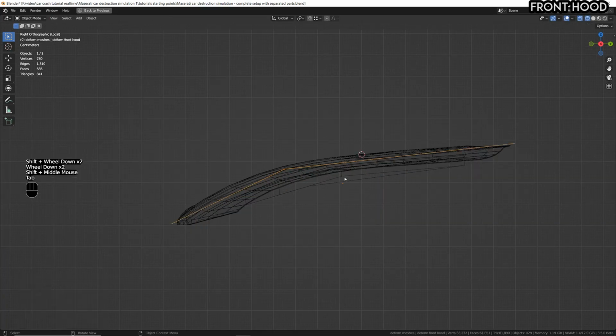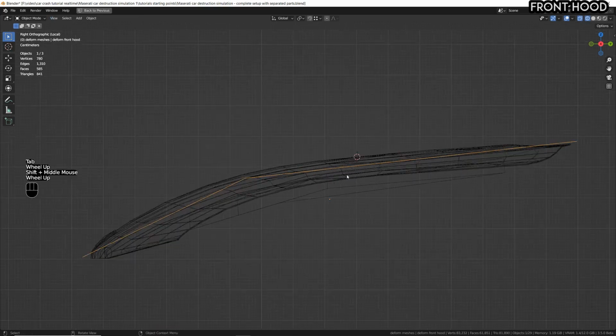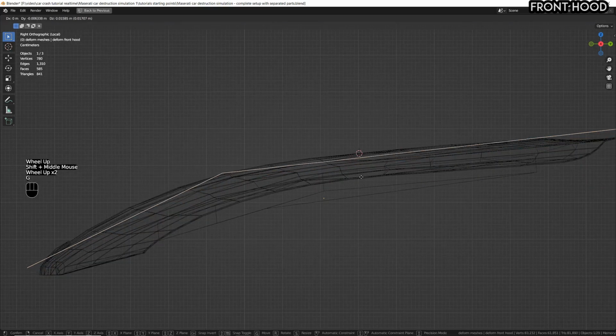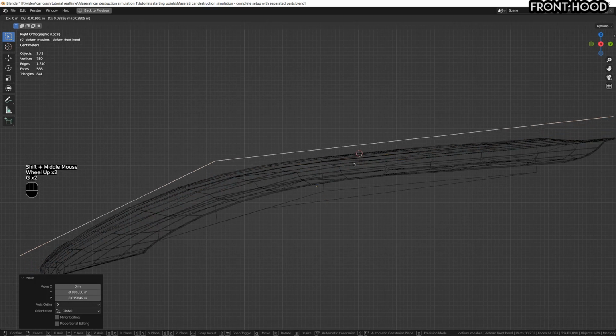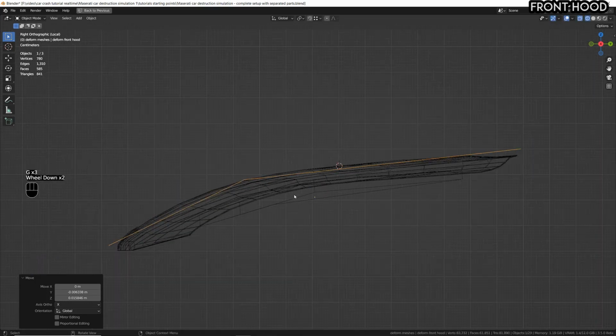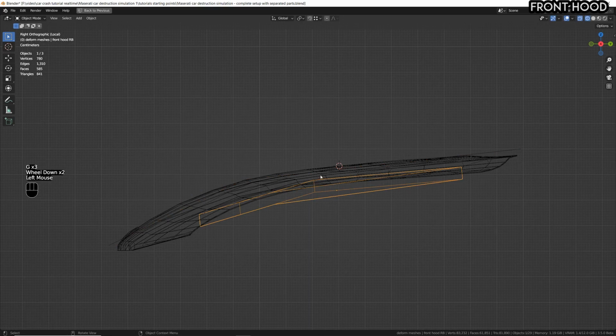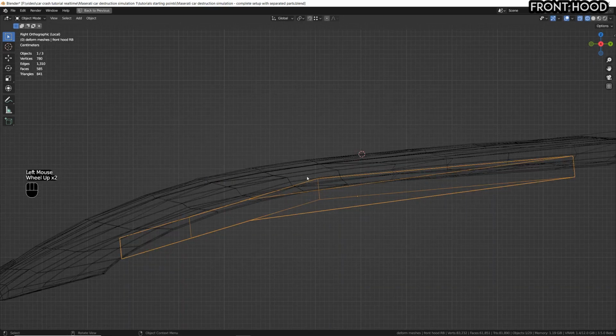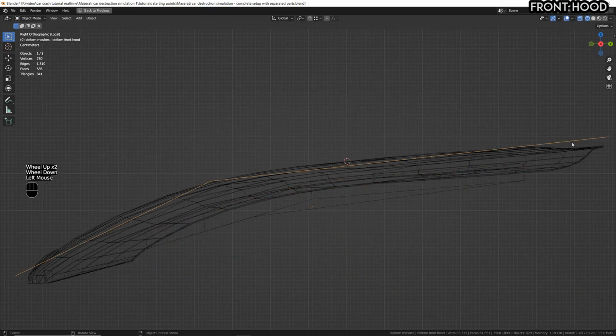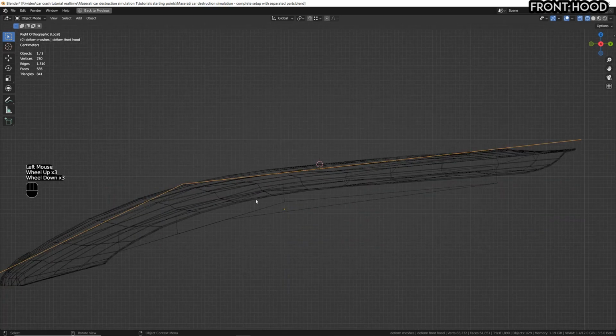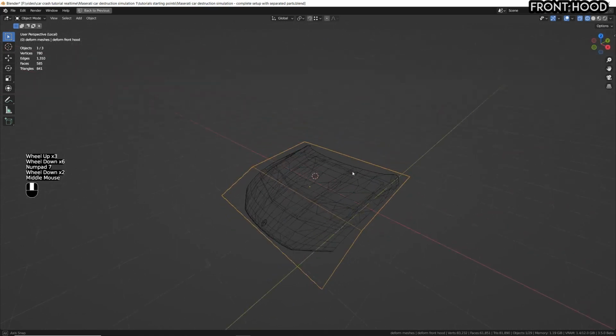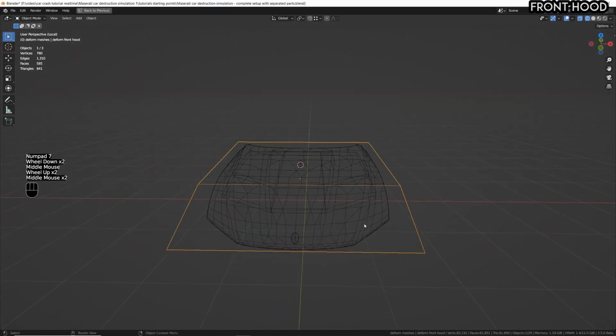Then a particular thing about the deform mesh is that I want this to be almost outside, like this. Not completely outside, but almost outside the original hood. So the rigid body is much lower compared to the original hood. Instead, the deform mesh is almost outside, but it should actually intersect a little bit. So let's see the shape that we got. Yeah, this is more than enough. We can edit the shape a little bit.